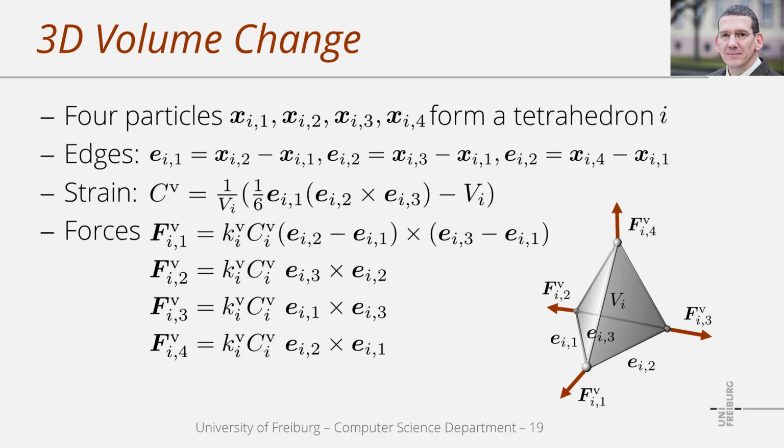That's it about some examples. We have seen how to derive elastic forces in cases where the strain can be expressed with one scalar value dependent on the positions of the particles that form an element. For the strain, one can actually use arbitrary formulations as long as the expressions base on particle positions. The same concept can actually be also applied to more complex deformations where the strain is expressed with a 3x3 matrix, but this is not part of this presentation.